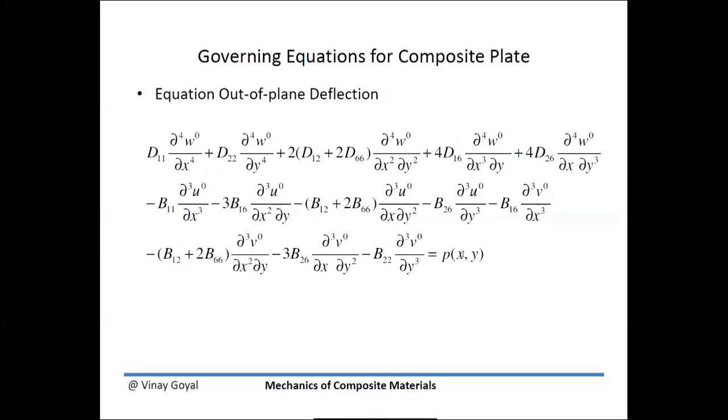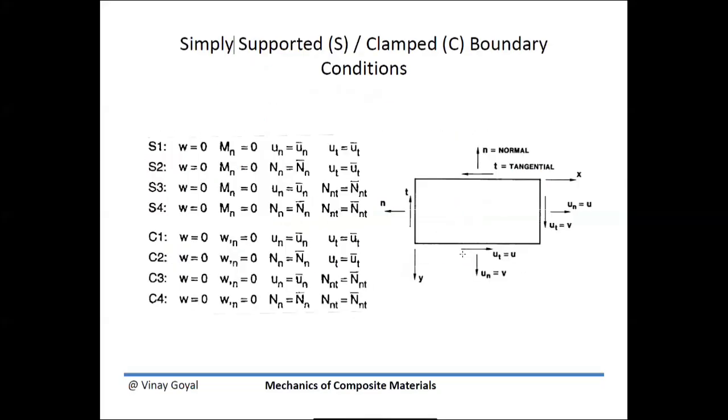You will do this through finite elements. And the boundary conditions typically are going to change depending upon what you're looking at. So for a plate with simply supported boundary conditions, which are basically rollers at each edge, the deflections are zero at those edges. For a clamped plate, you're going to have a situation where the deflections are zero, but also the slope is zero.